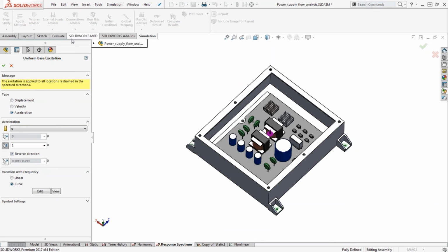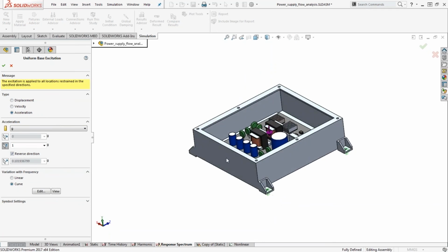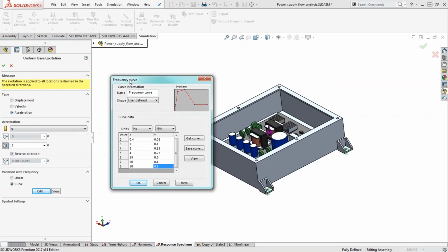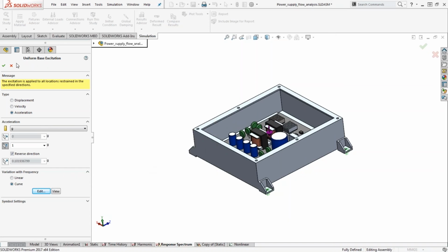And again, the inputs are going to be very similar, where you have to apply some sort of definition, you have to apply some sort of restraint, but now instead of some sort of load or pressure, you're inputting that response spectrum data. Usually it's going to be some sort of acceleration or velocity versus frequency. And then the unique thing about the results is that we're getting the peak response of the stresses, which means the worst case scenario or the max response of stress and displacement based on this seismic behavior.